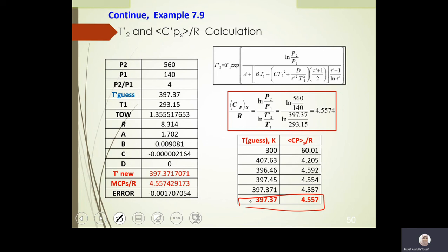Now look at the value. Delta T is so small, less than 1 degree C difference. And this is very normal with the pump. And that's why I said here it was based on the assumption that the temperature is just changing very slightly. The temperature change is very small. And based on that assumption, we had those equations. And I think you can clearly see that the temperature difference is very small with the pump. I'm done with the pump in terms of calculating the work, calculating the temperature difference.